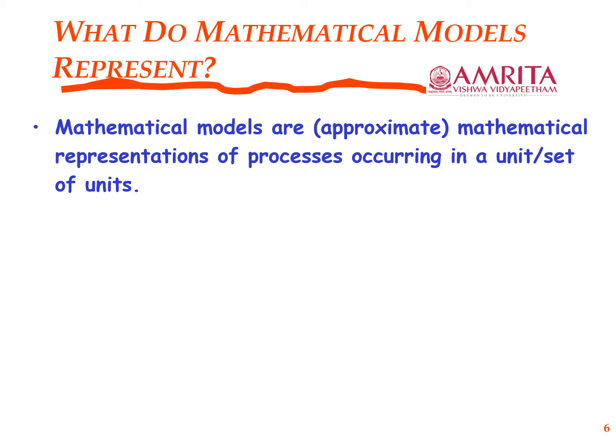Mechanically also, it is a very good approximation that the vapor and the liquid phases are at almost the same pressure. Chemical equilibrium, not a whole lot. I mean, yes, there would be some stage efficiency. You want to maximize that stage efficiency as much as possible. And so in all of these manners, we are writing equilibrium relations. They are not necessarily fully met in the unit, and therefore those are approximations.